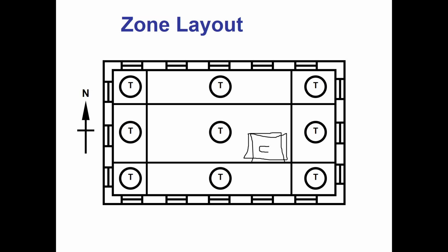Now, it is significantly more difficult than a constant volume system, especially if I have diversity going on, right? If I've only sized it for 80% of the airflow, well, now it's really hard. I can't balance it at 100% and get enough airflow to all my zones. So I've got to kind of divide things up in chunks when I'm doing the balancing. But I need to balance the VAV boxes and the diffusers.